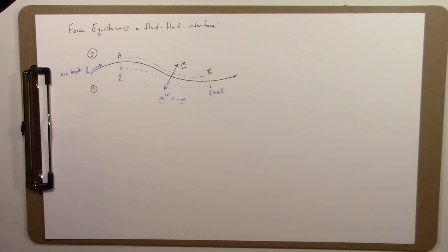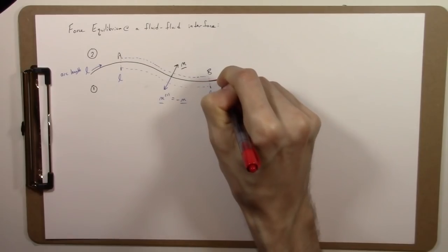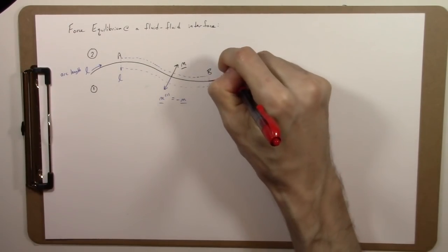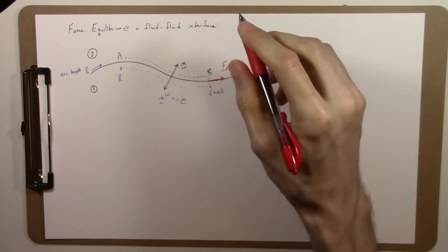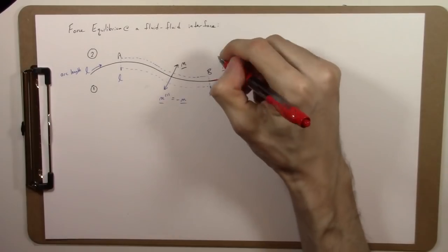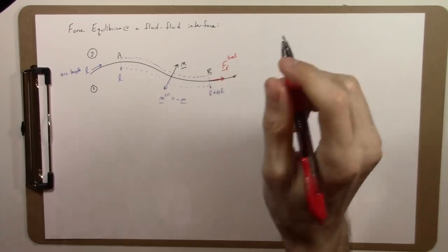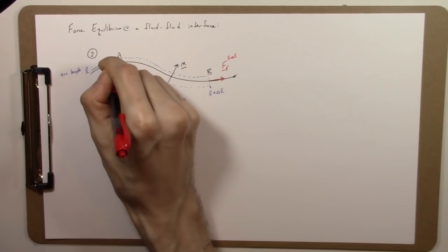So interfacial tension is a force per length that's exerted in the plane of the interface. So for example, there's a force being exerted here in this location of the interface. We call this F sub gamma at location L plus delta L. Likewise, there's a force here, and these are tensions, so they're always pulling outward from the control volume.